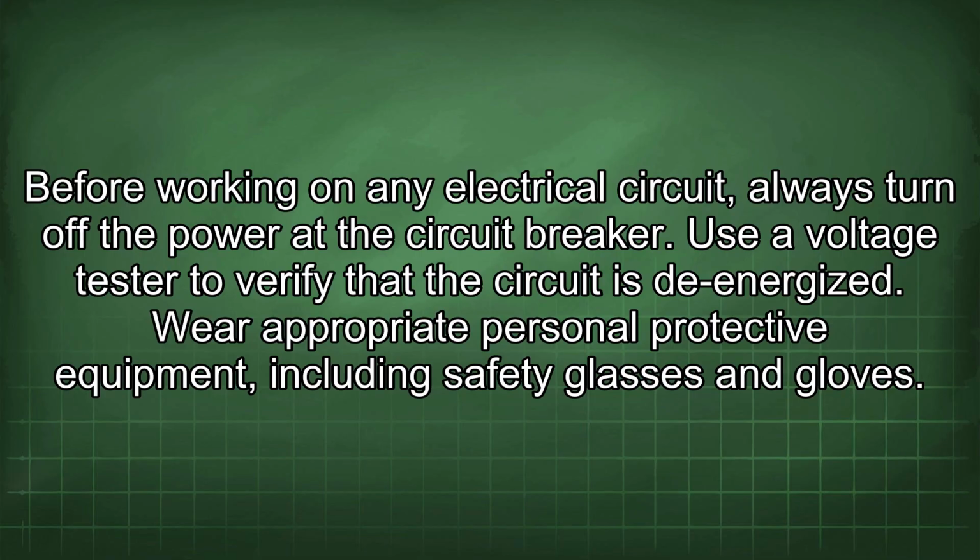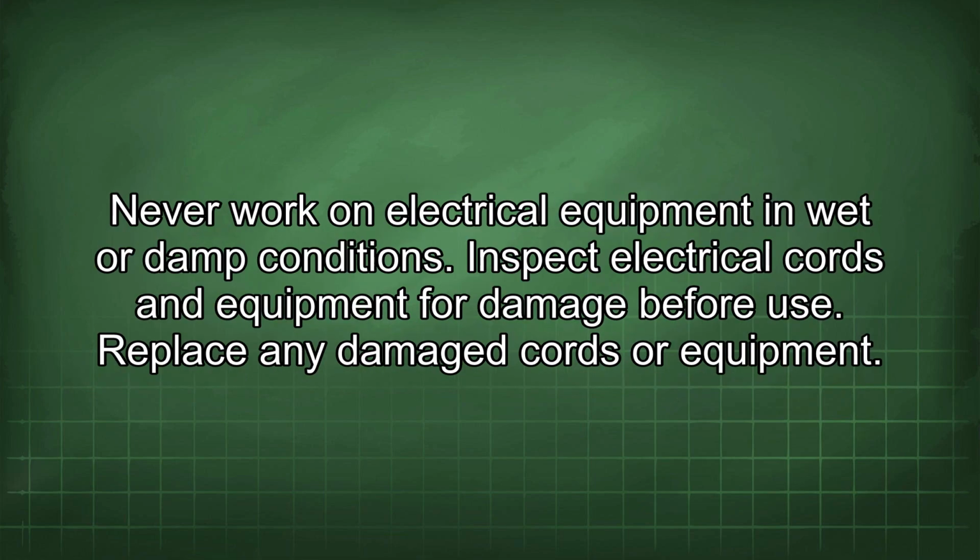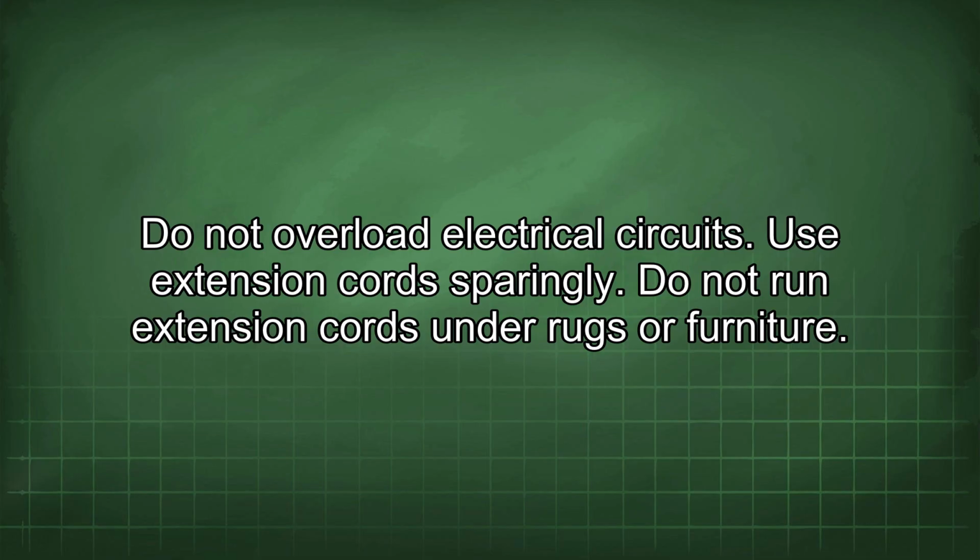Wear appropriate personal protective equipment, including safety glasses and gloves. Never work on electrical equipment in wet or damp conditions. Inspect electrical cords and equipment for damage before use. Replace any damaged cords or equipment. Do not overload electrical circuits. Use extension cords sparingly. Do not run extension cords under rugs or furniture.